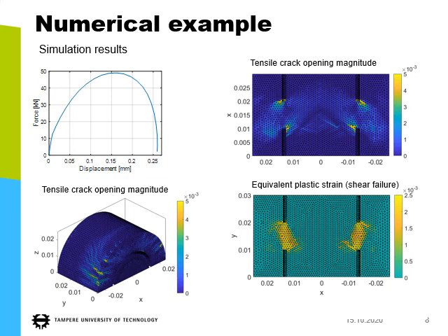So you can see here the equivalent plastic strain patterns, and this represents the shear fracture. So it is expected that this middle part is removed as in the experiments. So that much you can predict or say on the basis of this simulation. And you can actually also see some radial cracks here.